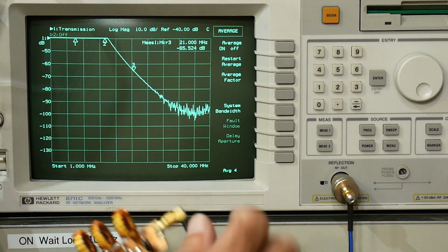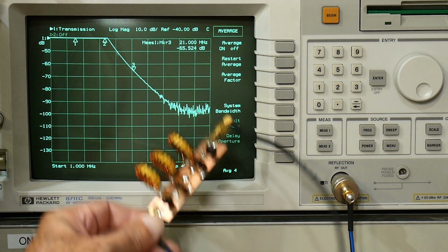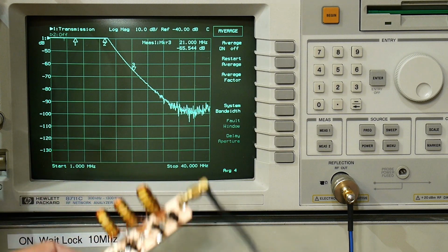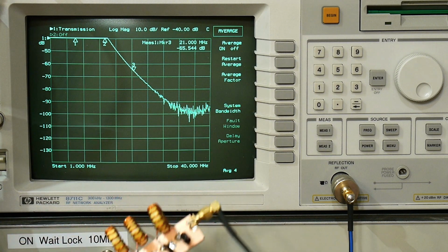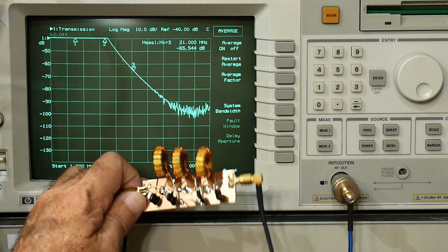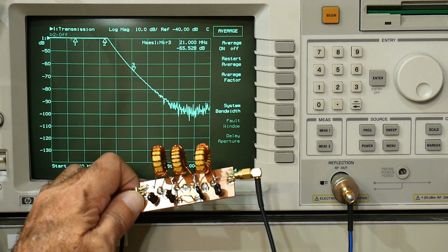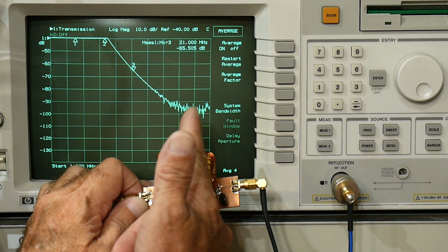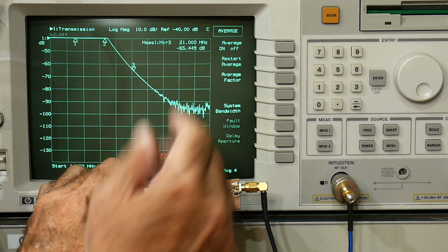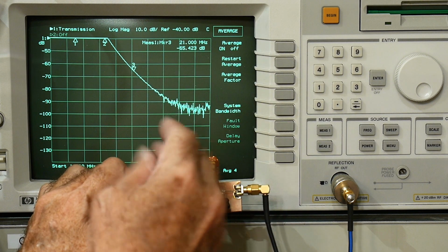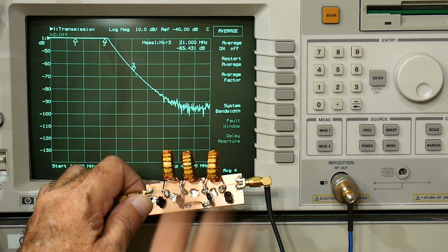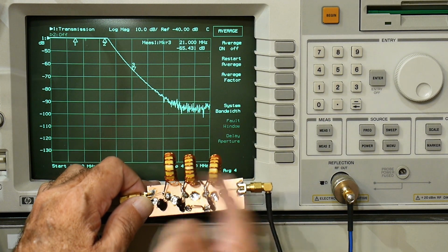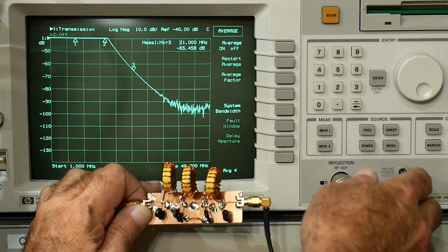making sure everything's okay. And then once you get a filter made and it looks good on paper and you've built one, then it comes to the point where there is a lot of mechanical considerations on filters. If you see some filters, each section is separated, and there might be a feed-through capacitor, and there might be actual Faraday cages around each section of the filter so that there is no crosstalk.